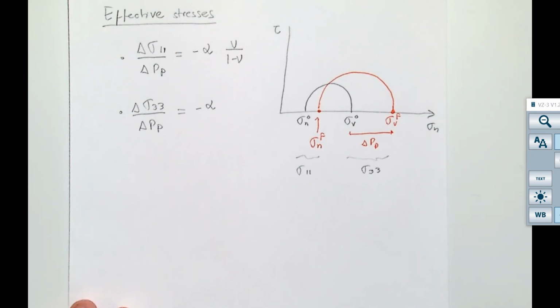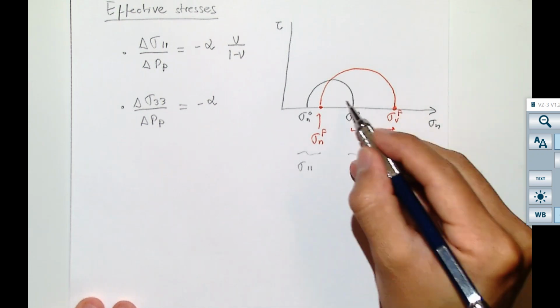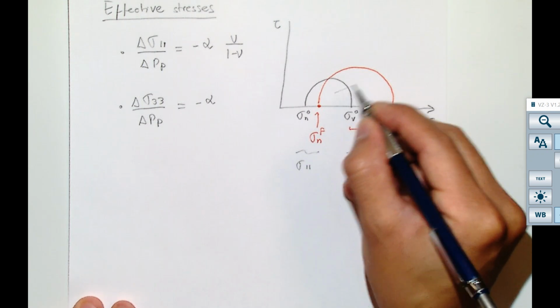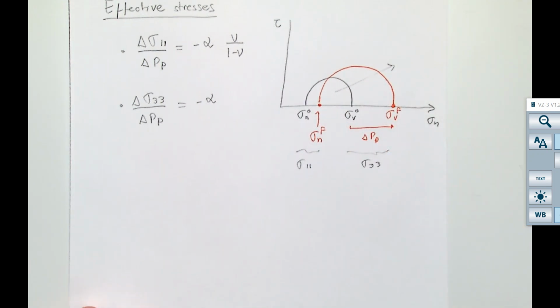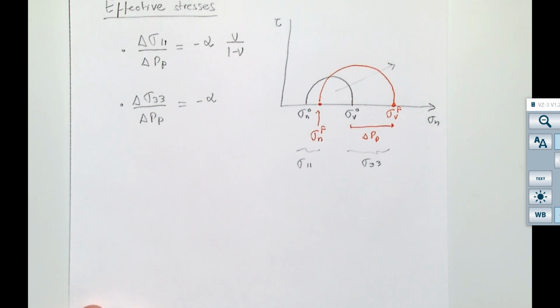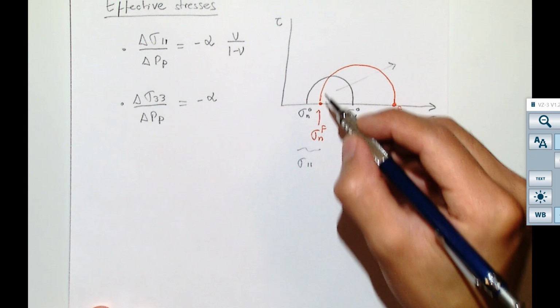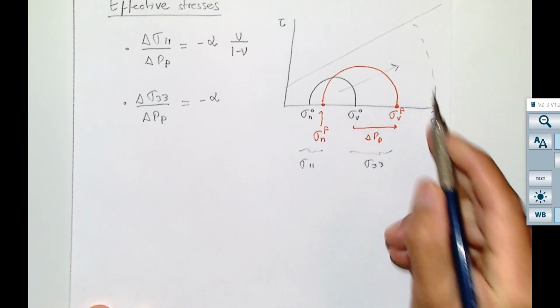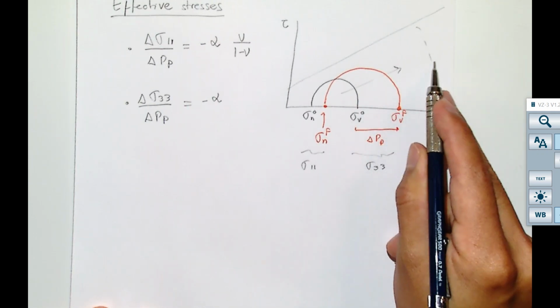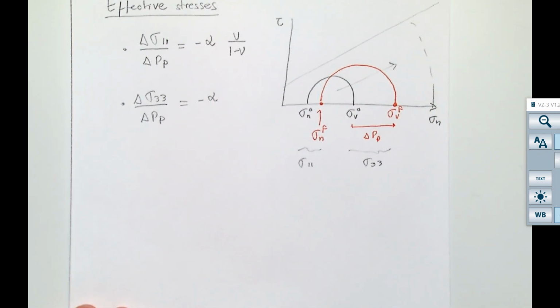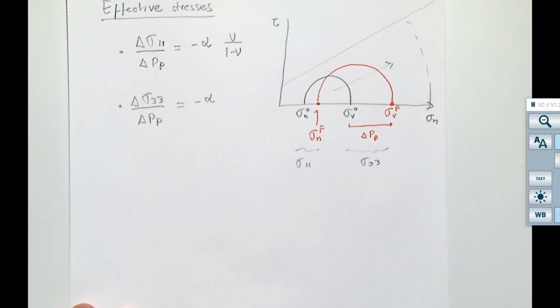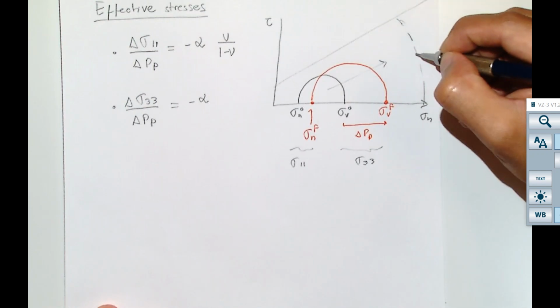So as you deplete, the Mohr circle is always going to grow towards the right, which means more compression, and it's also going to move up, which means more deviatoric stress. And if you remember that we said that whenever we have a lot of compression, sometimes we can run into this compression limit, that if your Mohr circle goes beyond that, you start to have grain crushing. So we're not going to get into that, but remember that that was something real.